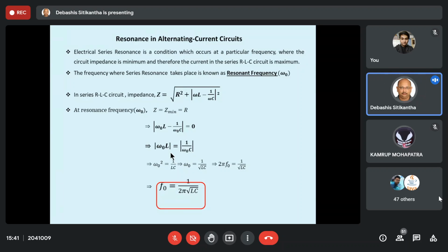Now, if you notice clearly, when you are traveling at 30 kilometers per hour, that noise is coming. Why? It is because at 30 kilometers per hour, the engine vibration is matching the natural frequency of the fuel tank lid. That means everything has a natural frequency. You have a natural frequency, I have a natural frequency.